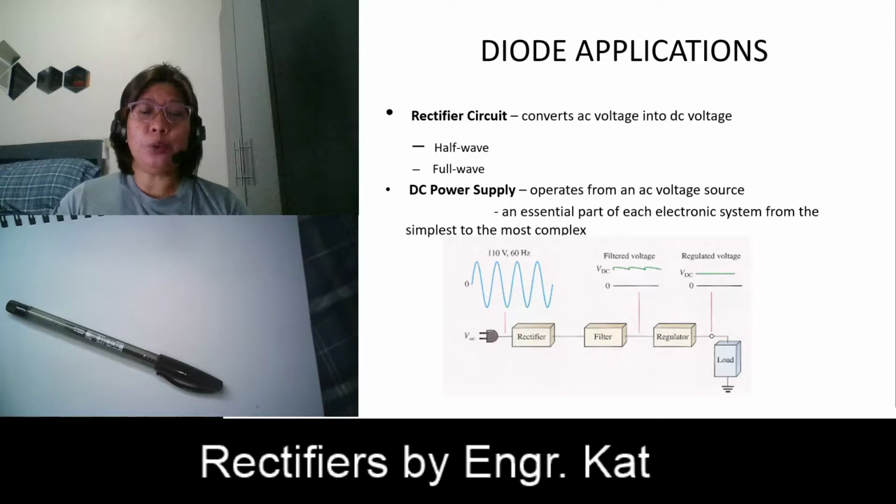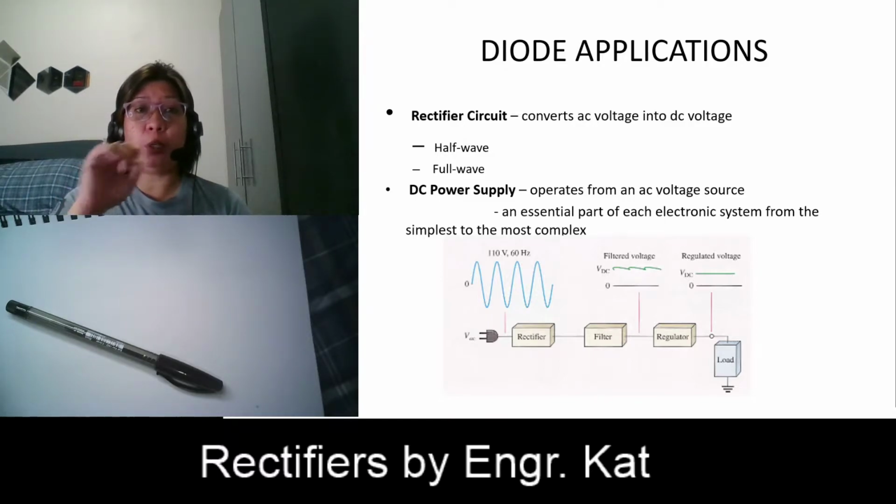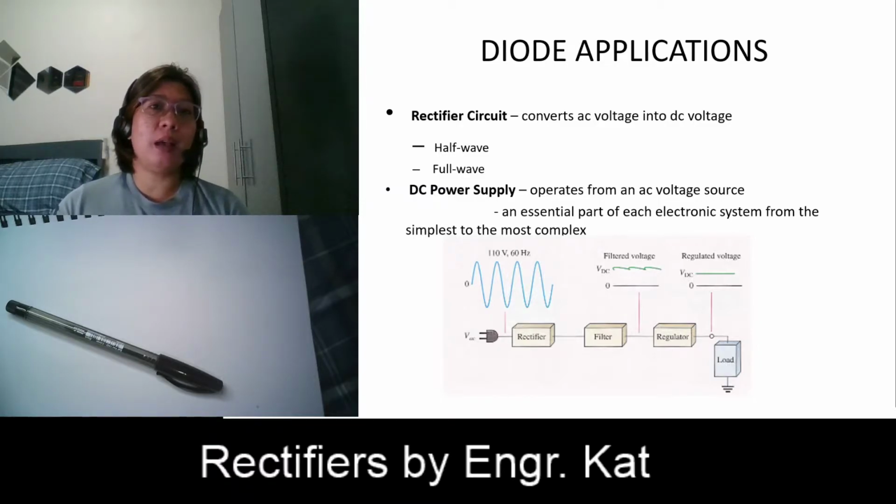Later on, we're going to find out that there is a relationship between the RMS value, the peak value, and the peak-to-peak value. But if we make use of an oscilloscope in your laboratory, usually what we see there is a peak voltage or a peak-to-peak value, although there are some oscilloscopes that are capable of giving us the RMS value also.